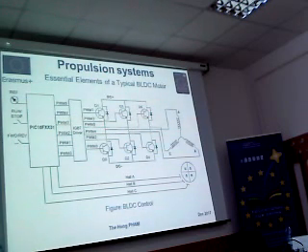So first from A to C, and now from A to B. So at the next 60-degree cycle, from A to B, Q1 is still open, and B is connected to Q2. So Q1 and Q2 will be open in the second cycle, and the others, Q0, Q4, Q3, and Q5, will be closed.